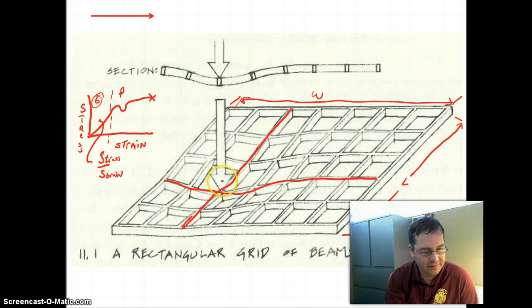Well, certainly they have moved down the same amount at the point of this arrow here, but they would find that they would have different deflections if they had different lengths. Essentially, if you made this left to right beam twice as long, it would only develop a quarter the stress from the deflection, and so it would not carry its share of the load.